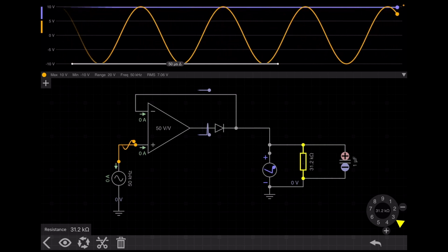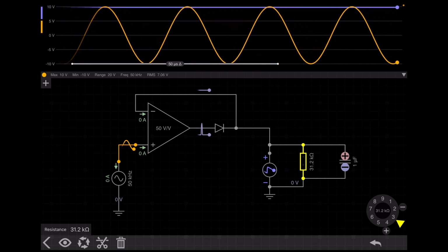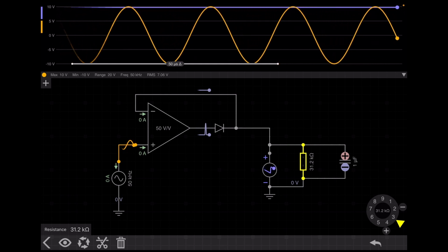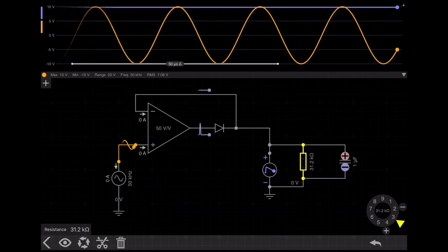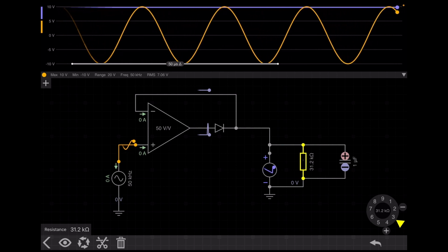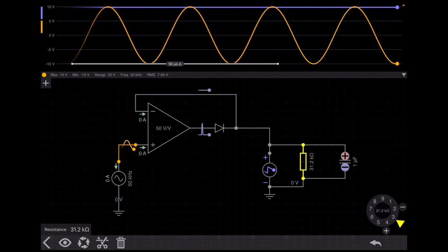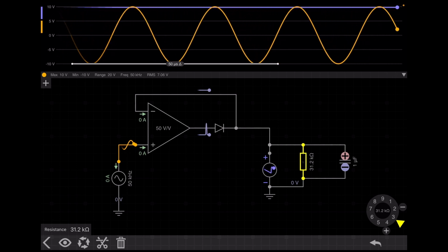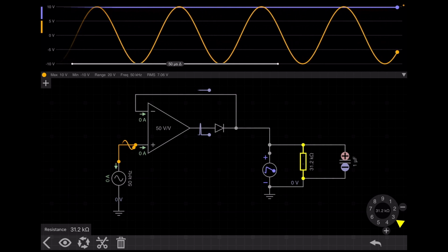Okay, I think you understand the concept. You don't need to write down everything in the paper. This is just for your concept. In the paper, just do the calculation and state that this is the half wave rectifier. I connect a capacitor filter, and as this is a capacitor filter without any resistance, there will be no discharge, as the time constant will be infinite. So it will just be a peak detector circuit.